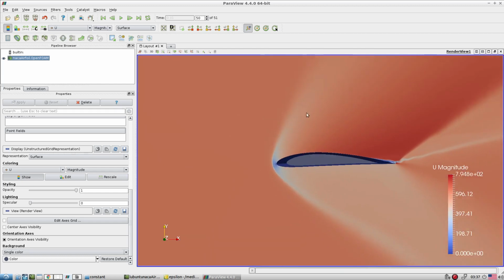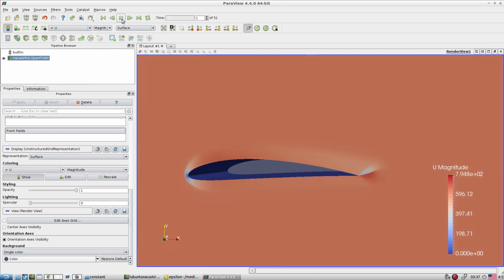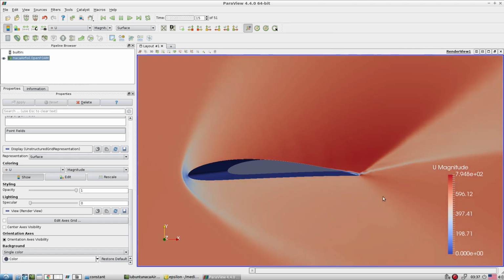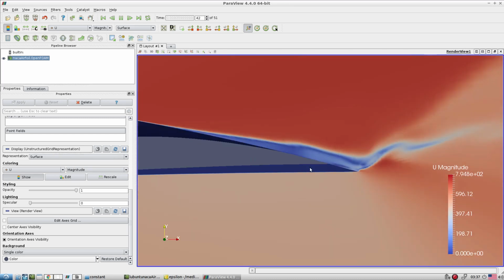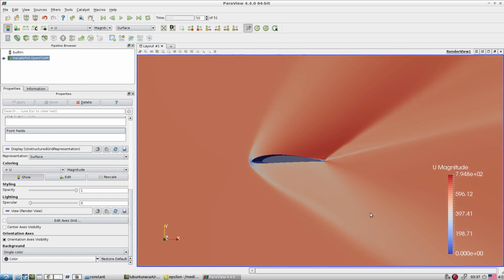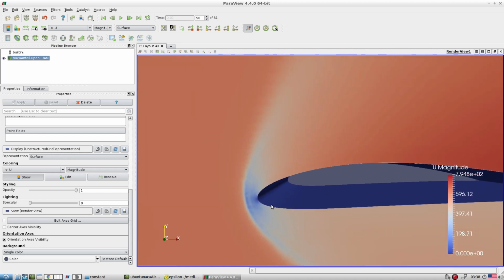So when the flow is approaching, just see what's going to happen. Slowly the shock, it is called the oblique shock, is developing. And at the back side you will see the nice shading. So that is what you will see in this domain. Vortex shading here, but the idea is that in this location you will see a sharp change in the property, not only in velocity.